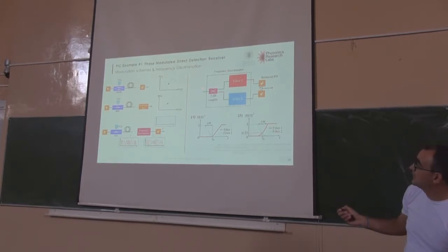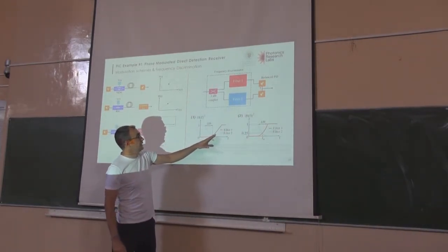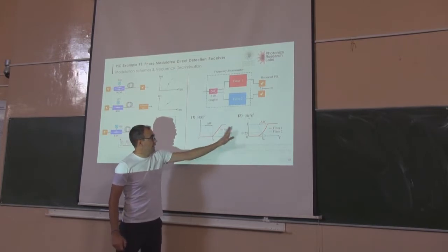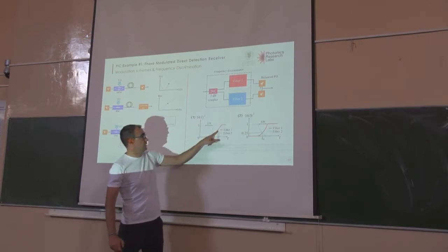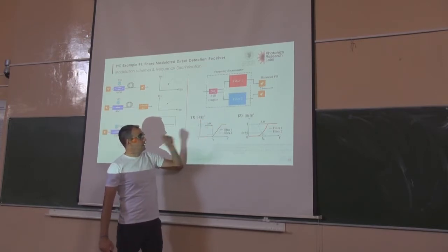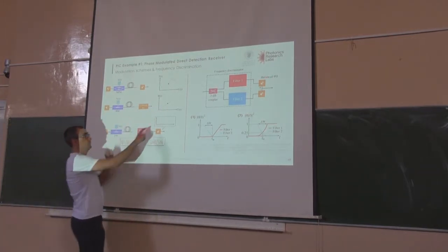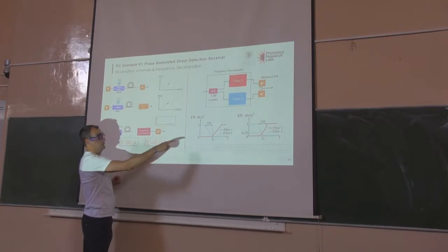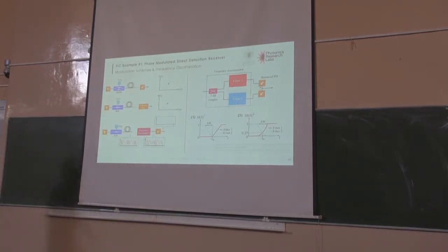A frequency discriminator, as I said, can be, for instance, like this: splitting your signal in two parts and then having two filters. One filter lets you pass the upper part of the spectrum, and the other filter lets you pass the lower part of the spectrum, the red and the blue filter. Okay? Then with a balanced detection, you can rectify the wavelengths because you get this from the blue filter, this from the red filter, but then you invert the sign of half a period with a balanced detector, and you have rectified your waves.